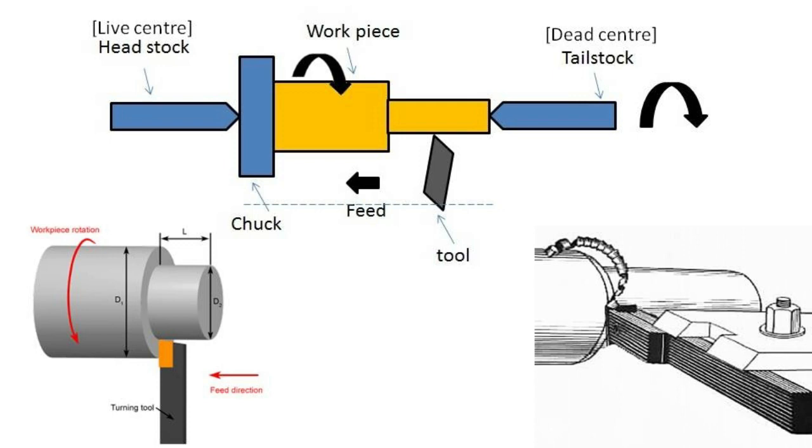Workpiece is held rigidly by one of the work holding devices known as chuck, and the tool is held by tool holder. Normally, a V-shaped single point cutting tool is held against the workpiece opposite to its direction of rotation. Tool is moved parallel to the axis of the lathe called lathe center axis to produce circular surfaces.